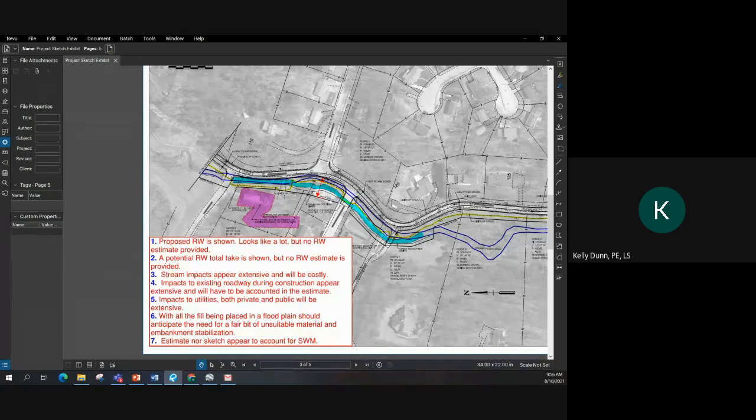And it's important to point out it is a pre-application, and so we don't expect it to be complete. We want to point out these things so the applicant takes a deeper dive into them. So yes, the slopes that are steeper than 2 to 1 are usually reserved for solid rock or engineered slopes. In considering a flatter slope than a 1 to 1, which may very well be necessary, the applicant may find the earthwork and right-of-way impact costs will increase significantly.